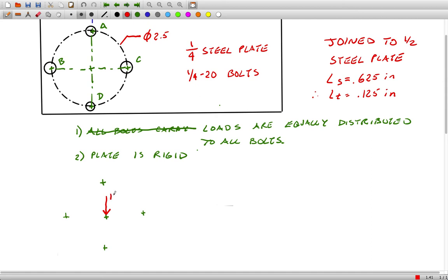So I know it's going to transfer to the centroid as a force, and then that's also going to create a torque. And here I'm drawing the direct loads exactly as they would look at that centroid. In other words, I'm not drawing reactions. I'm going to put the bolt forces in as reactions. So I'm going to have essentially a direct shear force that's a portion of the 1,000-pound force that acts vertically at all 4. If that splits evenly, that means that every one of those bolts has to contribute 250 pounds. We'll just say all forces given here are in pounds.